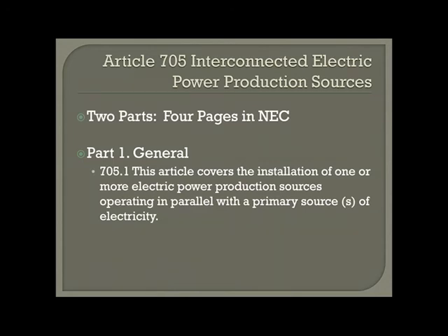How much power can I put back into that electrical system? They have requirements, and we really need to think about them requirements and do not overload that. I had one system this year that I turned down 4 times because I didn't like the load on it. And it actually started the panel in the house on fire. Luckily, the homeowner was home. And the reason was because of voltage drop, too small a wire, and too big a load. There was too much load going back onto that wire from the PV system and from the power being consumed.